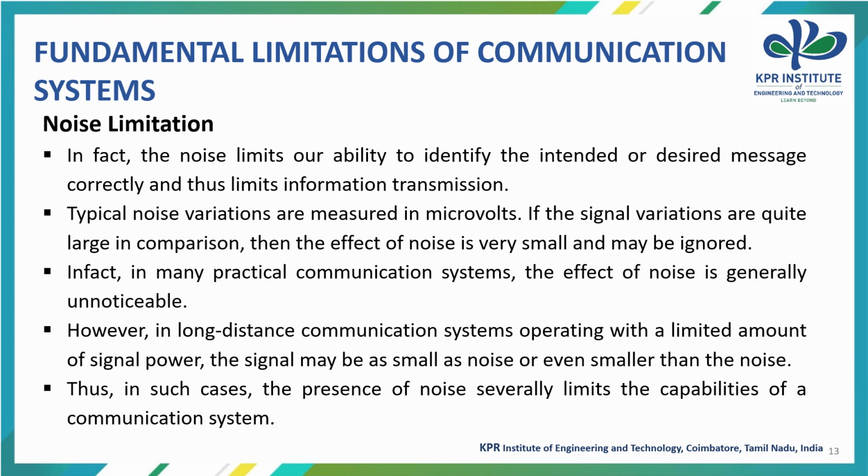In fact, the noise limits our ability to identify the intended or desired message correctly and thus limits the information transmission. Typically, noise variations are measured in microvolts. If the signal variations are quite large in comparison, then the effect of noise is very small and may be ignored. In fact, in many practical communication systems, the effect of noise is generally unnoticeable. However, in long distance communication systems operating with a limited amount of signal power, the signal may be as small as noise or even smaller than noise. Thus, in such cases, the presence of noise severely limits the capability of the communication system.